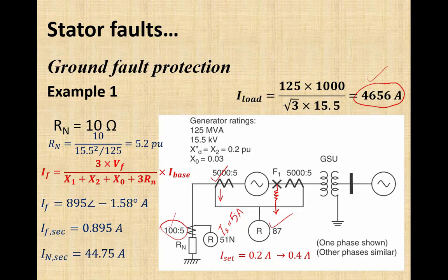In case of moderately high grounding impedance, the phase fault relay can detect a ground fault, but if we use a neutral connected CT and its secondary has an instantaneous overcurrent relay, we can provide very quick and reliable protection against ground fault.